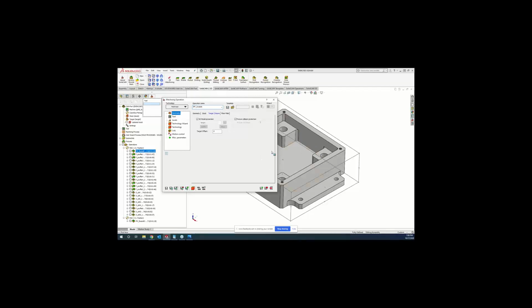I'll bring you into another part where we do have a fixture in there. We also have the option for floor fillets in here, but if we're cutting the outside of our part, we really don't care about that. For those of you moving over to 2020, it's going to look just a little bit different from what you're used to seeing. And then our last option is basically iMachining old school. So no feature recognition, no advanced stuff. You'd have to mark your chains open and close and so on and so forth.